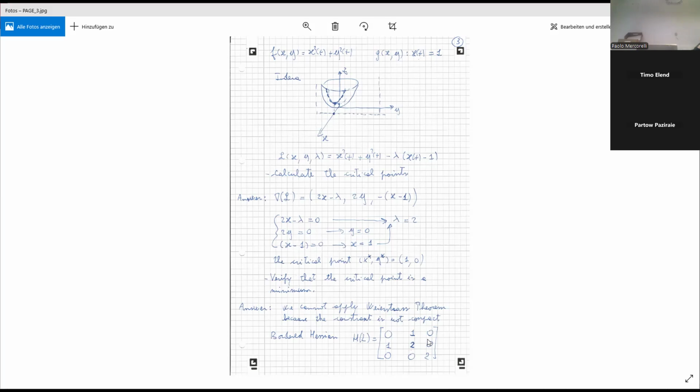If you remember why they depend on the input, if you remember the model predictive control I presented, we have an equation in which the derivative of the states equals a function of the states and the input. If you think about a possible discretization, we have seen exactly in MPC how I can discretize the system. This x and y, current and velocity, do you remember in MPC? As a function of, again, current and velocity and the input.